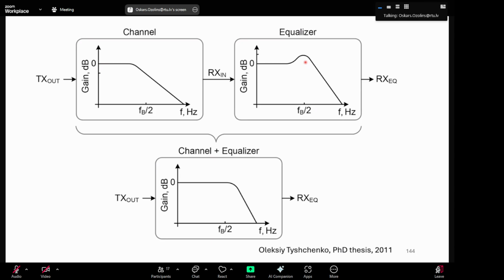Or, if I can say it simpler, what is the voltage swing available at the transmitter, then you can decide how strong an equalizer I will use in the transmitter, and how strong an equalizer I'm going to use in the receiver. And these are the things we need to optimize all the time to achieve the highest bit rate possible.